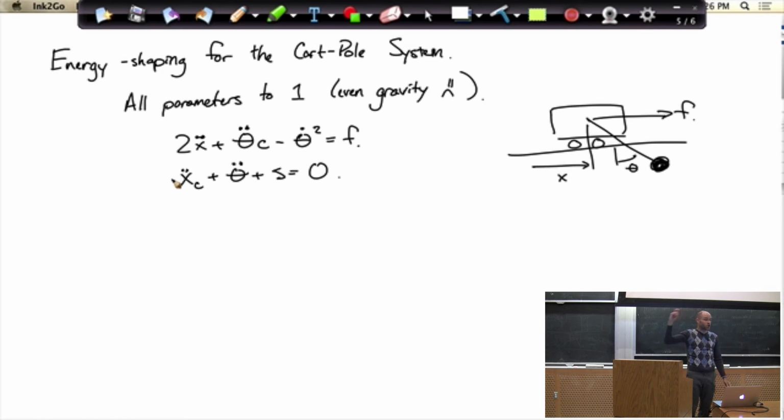So we're only going to reason about the energy of the pendulum, where it has this nice homoclinic orbit. We're going to make sure that whatever the cart's doing, the pendulum lands on its homoclinic orbit and gets up to its upright. Then we'll do some extra work at the end to make sure the cart does the right thing. The total energy is hard to reason about in terms of a simple solution that gets to some unstable fixed point.